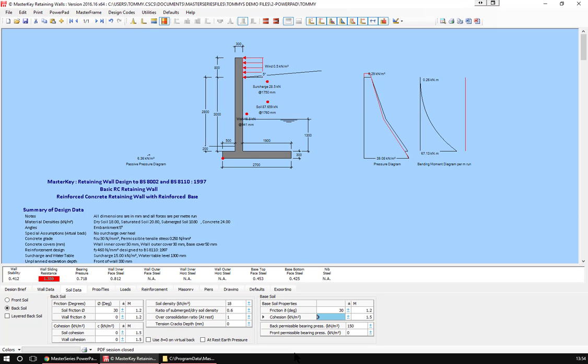It's not one I would recommend because people have been tramping around this. You've put blinding in and everything, so it's going to shear before that. It's very difficult in my mind to activate the cohesion here. Cohesion down here, yes, you can activate that and have an effect.